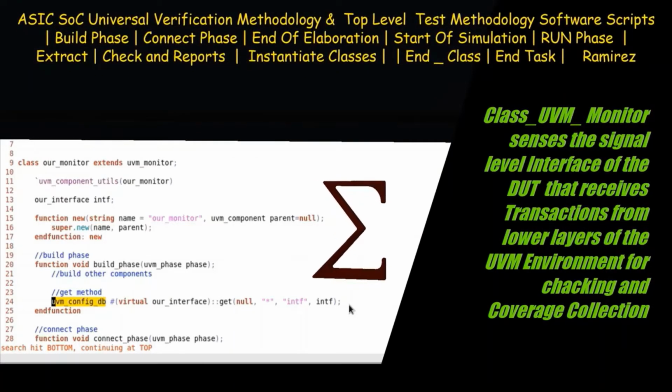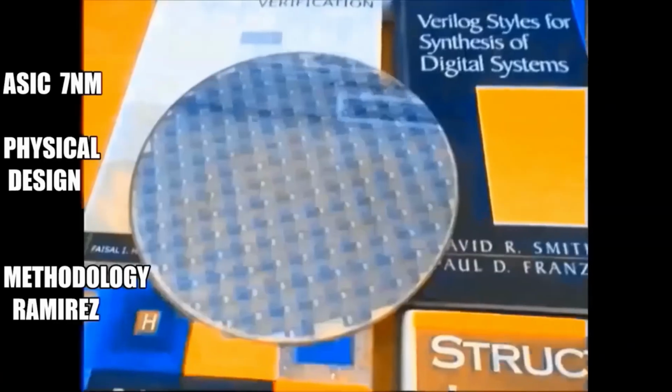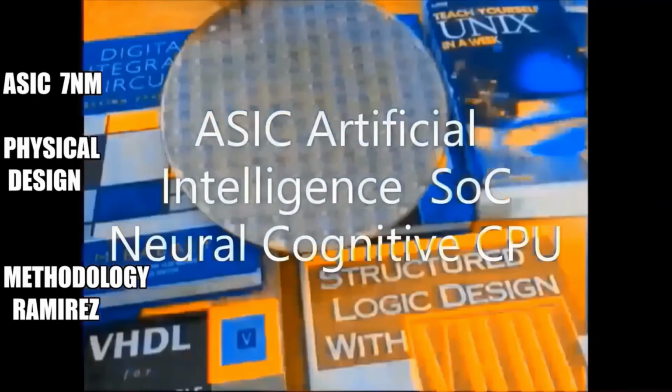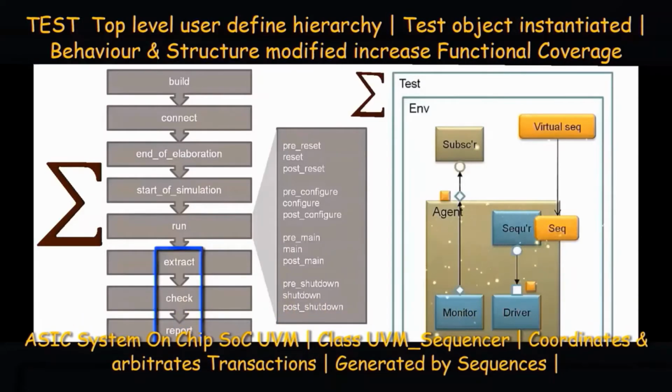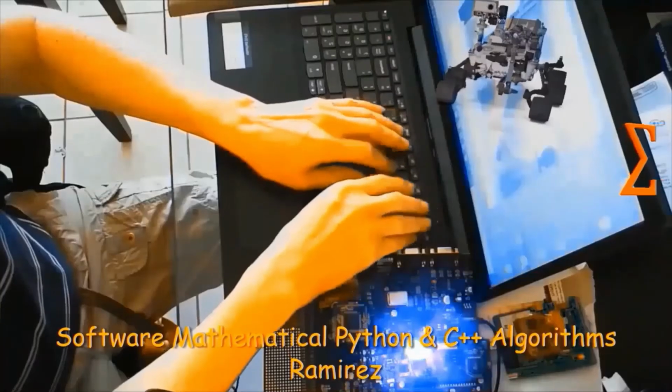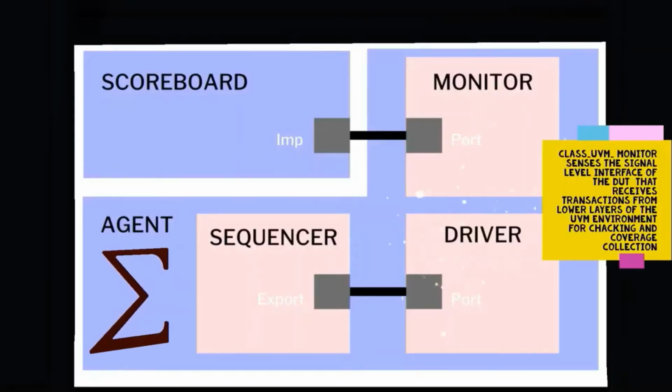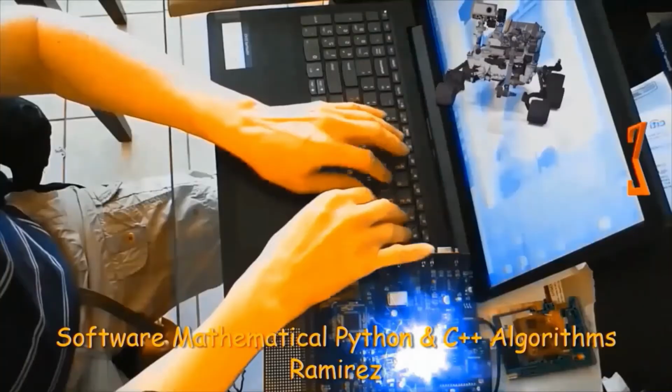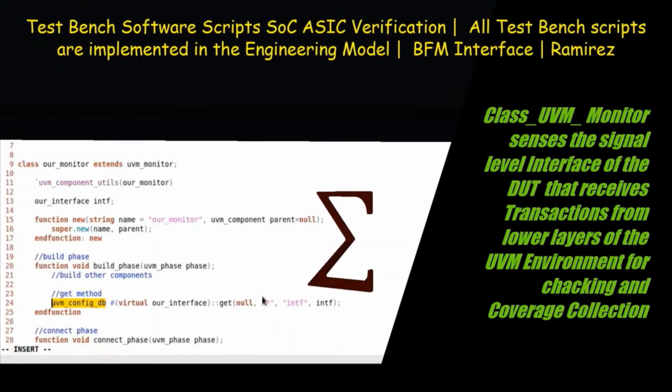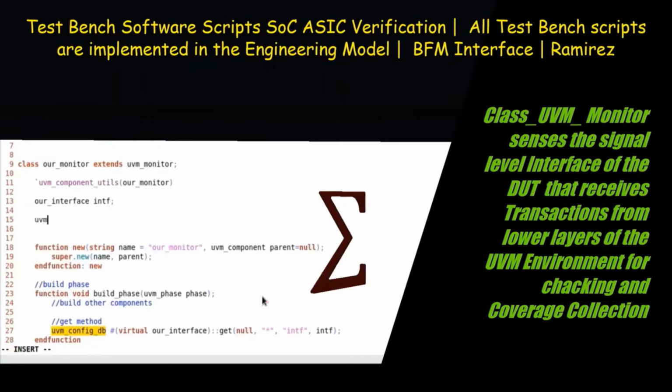The synthesizable test harness contains code to generate the clock and the reset, and the code to instantiate the bus functional models, the BFM, the pin level interface, and the DUT. The untimed test bench instantiates the UVM environment. So it is important to note the untimed test bench.